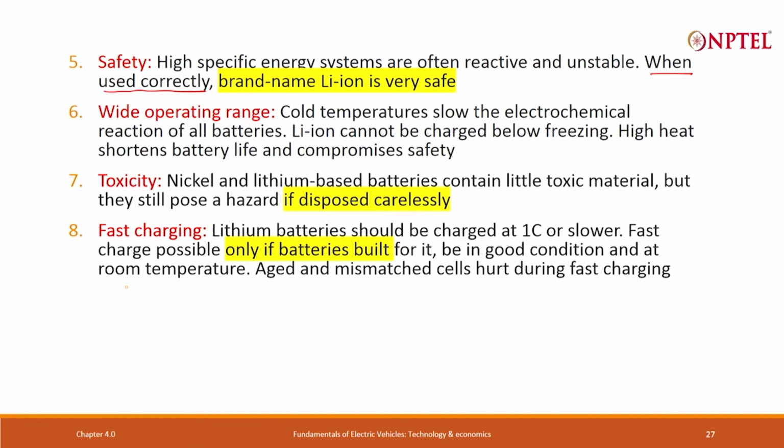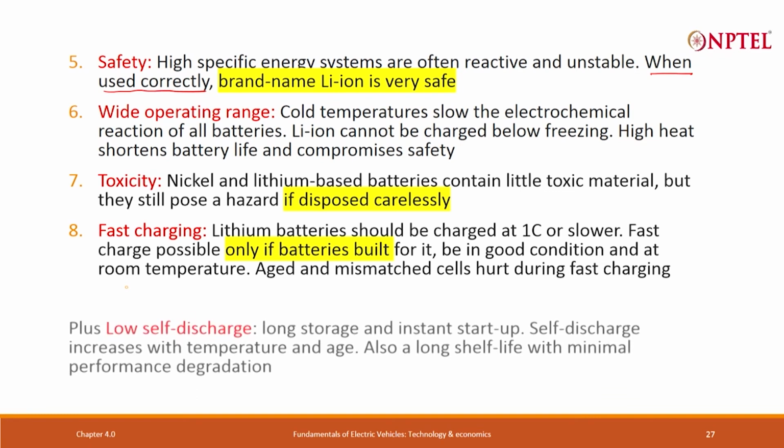And then fast charging. Fast charging is actually related to the C rate that I talked about earlier. Normally, a lithium battery should be charged at 1C or lower, but can I occasionally fast charge? Now, with a specific kind of battery you can, otherwise you impact the life very badly. So, these are the 8 asks.